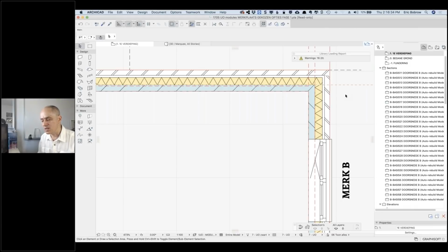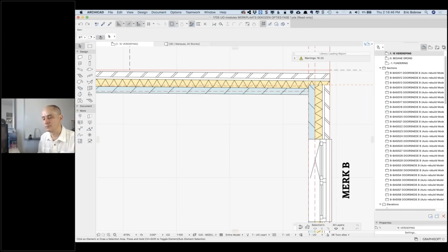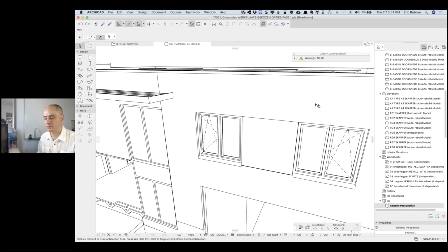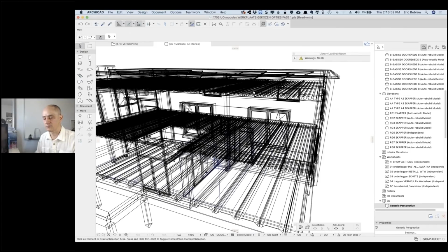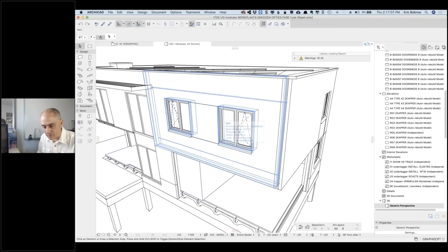But you were talking about pulling. Can you go a few steps back? Undo, because this is extreme, but if you go to the facade now, you can see that there is a closing line. Because for me, it was just a few millimeters. Yeah, so we get a bunch of extra lines there. You see the two window frames on the right side, and the line is closing between the wall on the ground floor and the first floor.